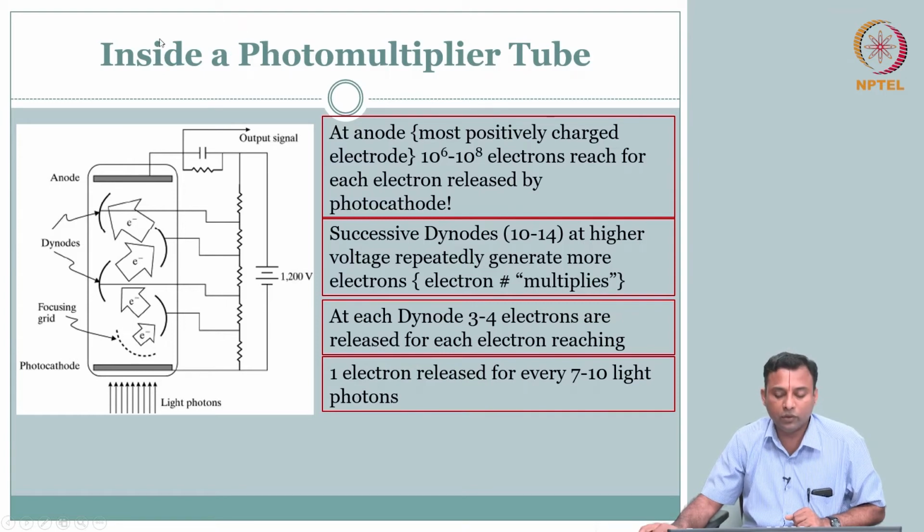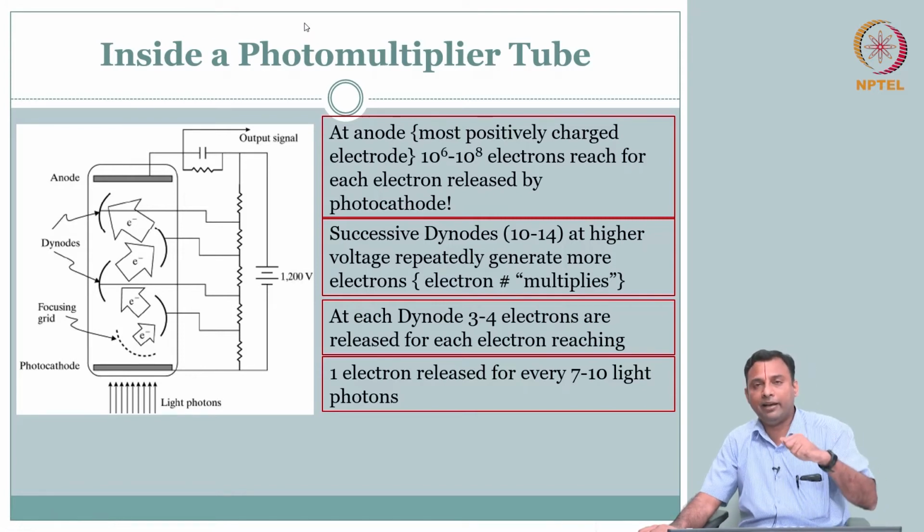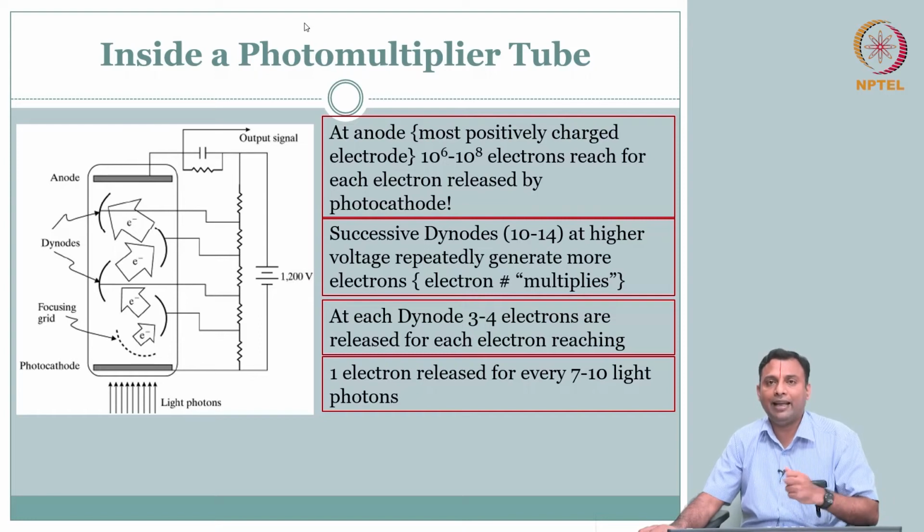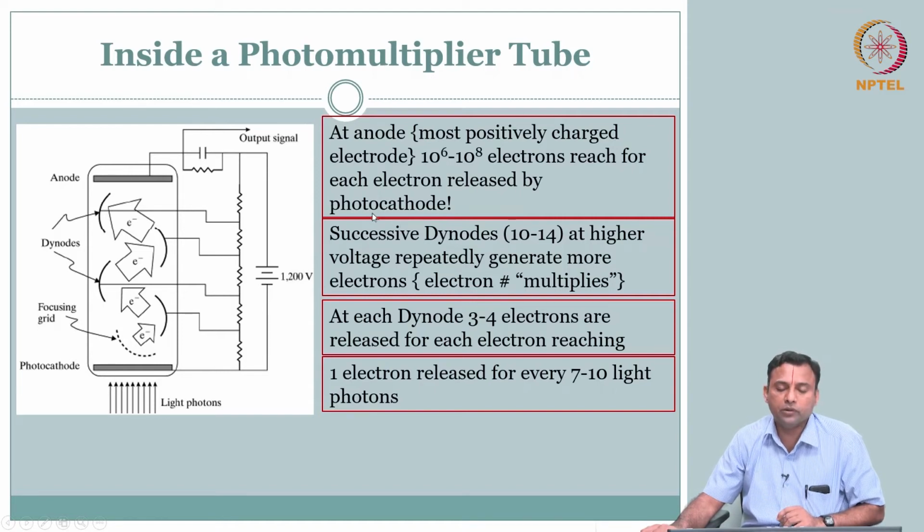Of course you can read this out as a voltage signal. So you have successfully converted the gamma rays into light photons, and the light photons are converted to your electrical signal. So you can read this out, that is your output signal. You get some millivolts to a few volts, in that range.